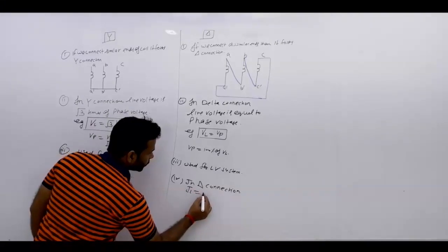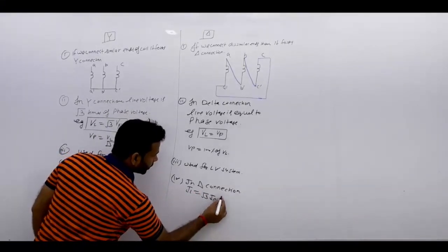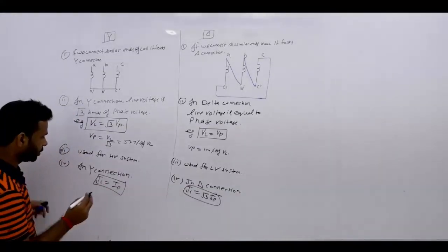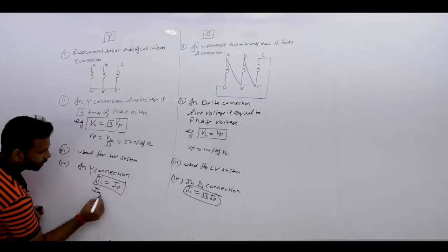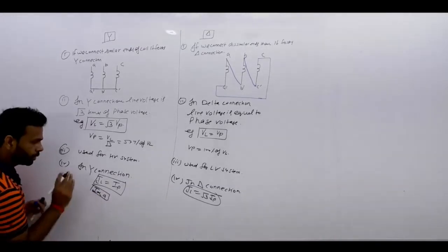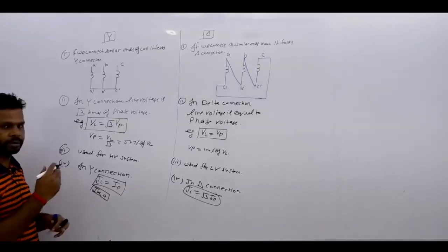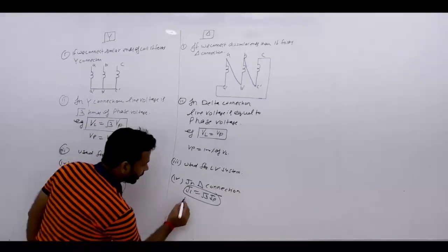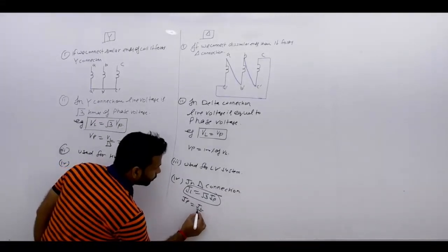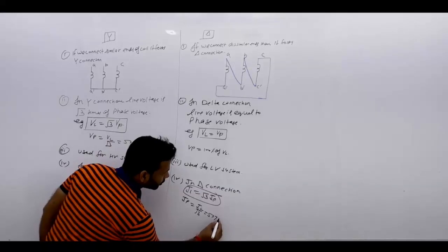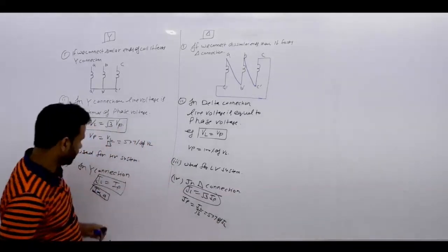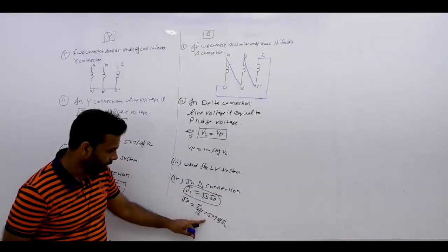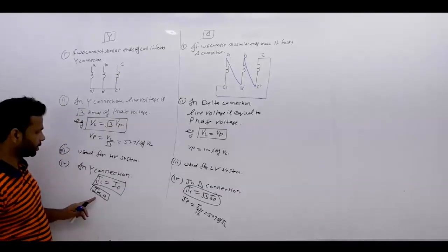Now here, if you take more current, then the size of the wire is more, because current is directly proportional to area. So if you use star connection for higher current rating, then the size is large. But here, if you see, IP is equal to IL upon √3, so 57.7% of IL. So the area or volume of copper wire required is 57%, while here it is 100%.